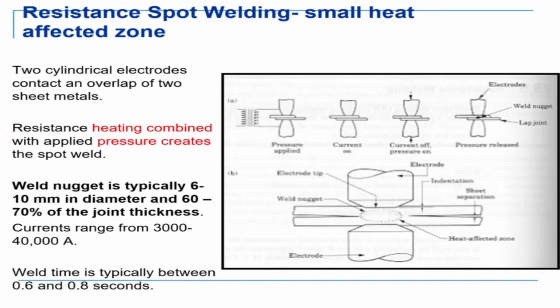The basic process of spot welding, as you might have studied in other courses in manufacturing, is that there is an electrode on both sides. So we have an electrode here and an electrode there, and these are the 2 sheets. There is one thin sheet here, another sheet here, and a current is passed between them. Because of the heat generated in the center by the I square R heating, the metal will melt there, get fused, and that's your spot weld.